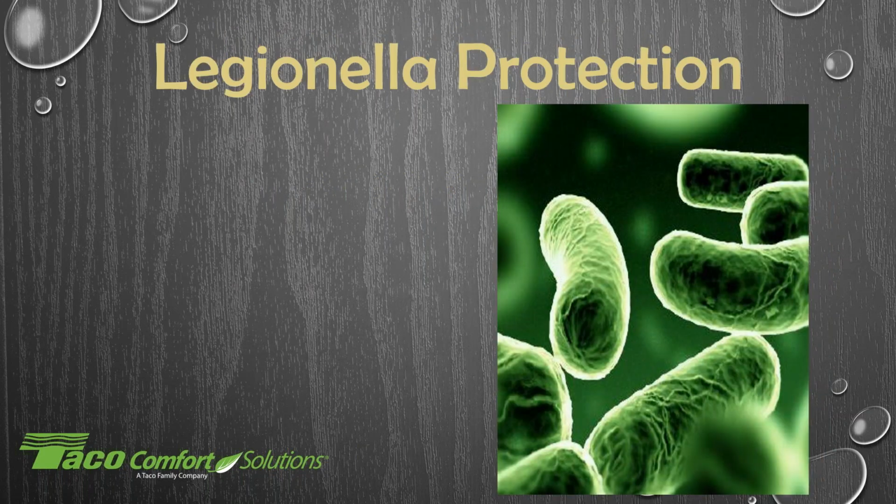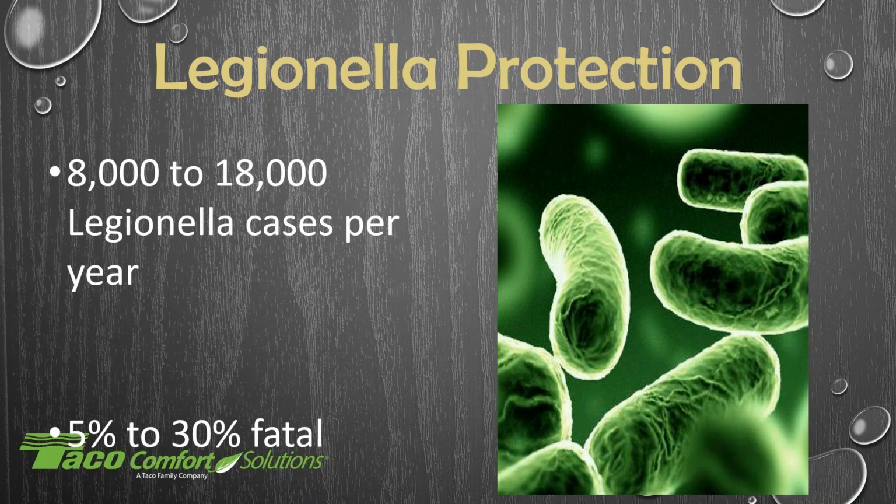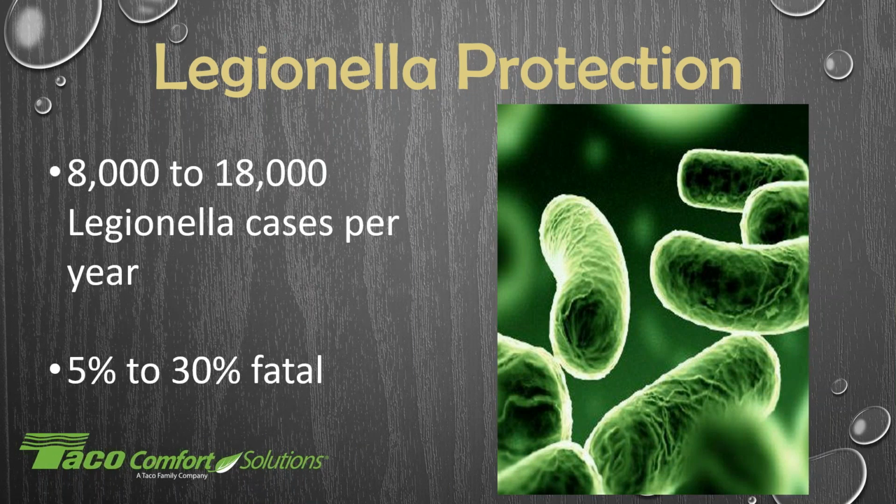Another reason to consider mixing valves in your system is to prevent Legionella. Legionella protection. In order to get rid of the Legionella bacteria, we can heat up that water periodically, or keep it a lot hotter in the tank itself to help kill that Legionella. But if it's too hot, now we have that issue of scalding again. So those are other reasons to think about adding mixing valves into your systems.